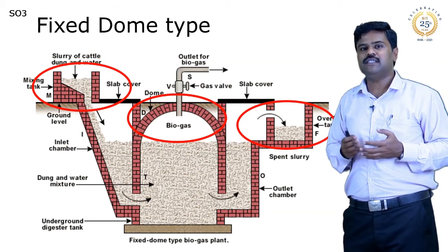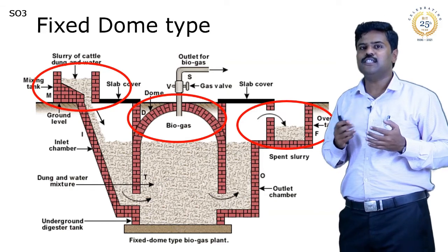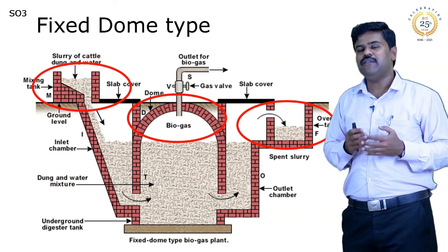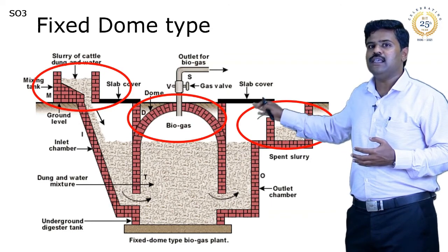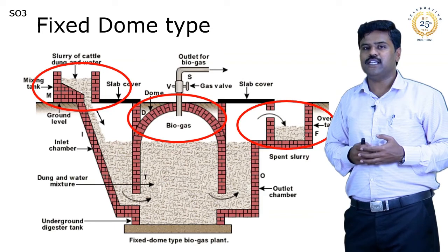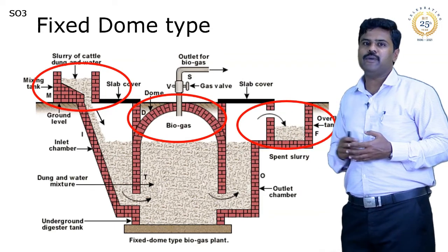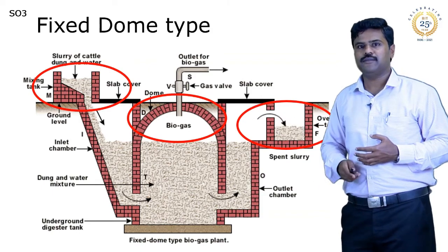This model has several advantages like less investment, less maintenance and less manpower. But it has a risk of explosion. If the pressure accumulating in the headspace crosses the threshold limit, it is going to cause an explosion. So we need to operate this fixed dome model in the presence of trained technicians.